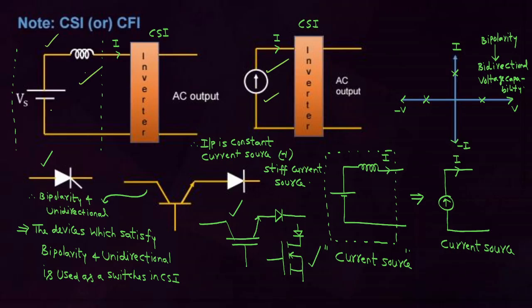The switches having bipolarity capability. That means they block both polarities but conduct only in one direction. Those switches are used for the current source inverters, or current fed inverters. That you have to concentrate on.